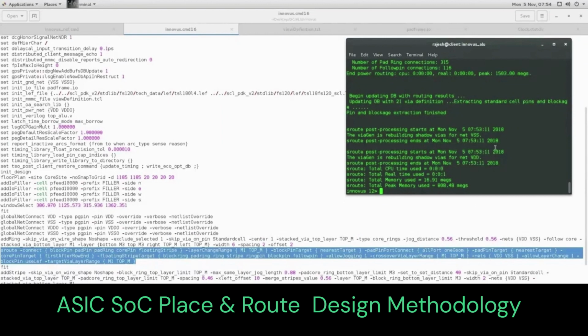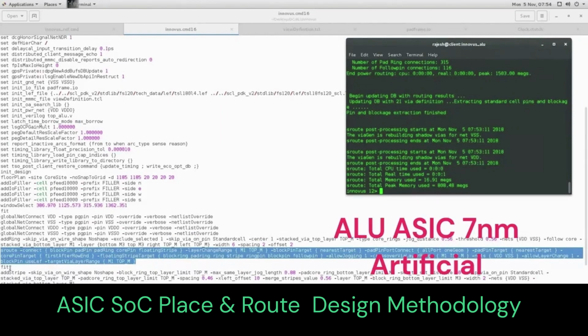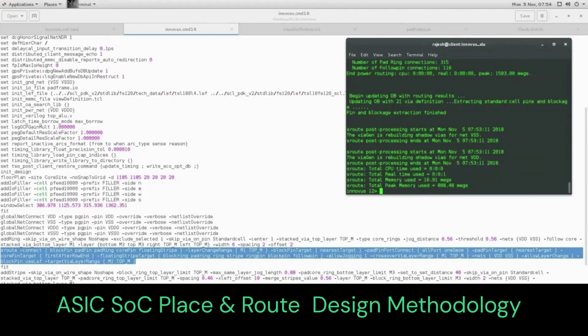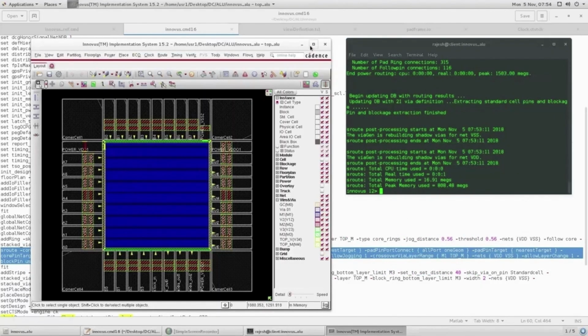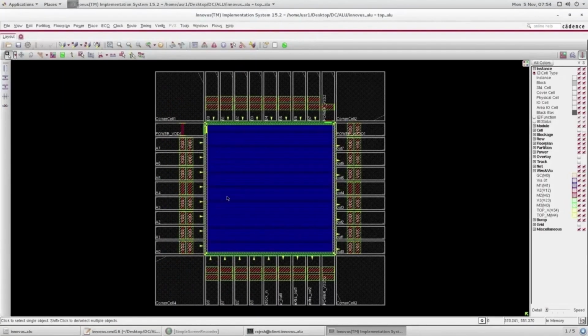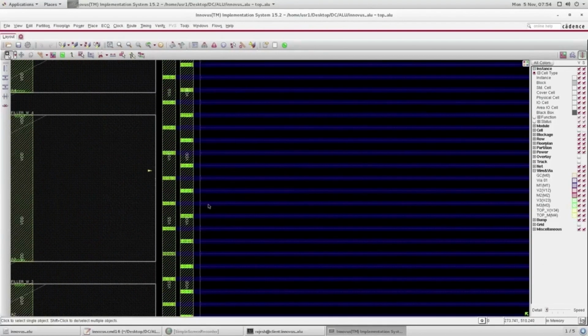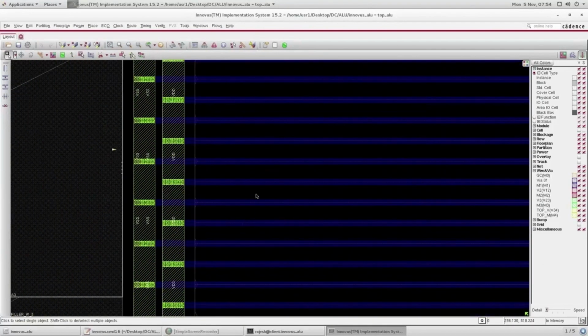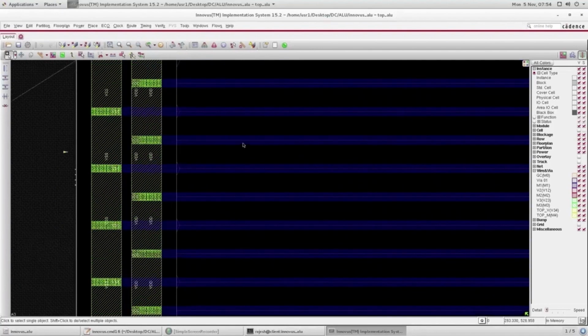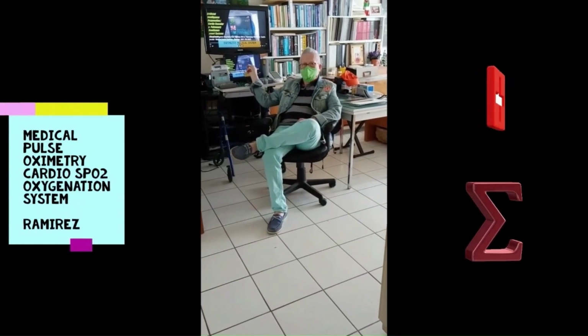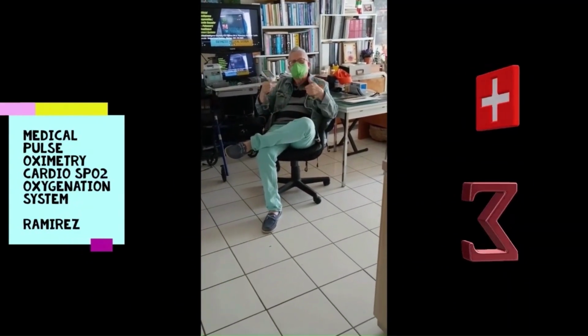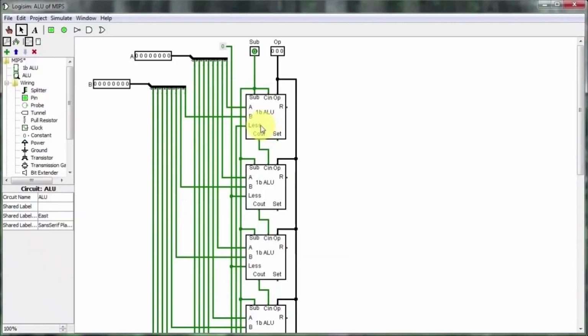Fifth, perform placement. Sixth, optimize the clock trees and scan connections. Seventh, make logic changes, including changes to circuit power levels, to fix timing problems. Eighth, legalize placement. Then generate the new timing constraints for wiring on the basis of a timing analysis done using the actual clock tree and wire load and RC delay values derived from the final placement. And then finally, perform routing.